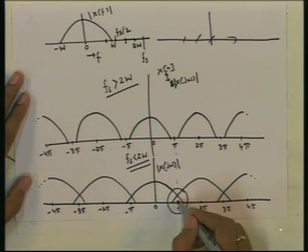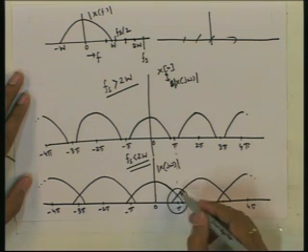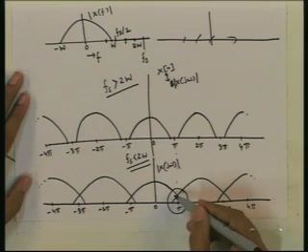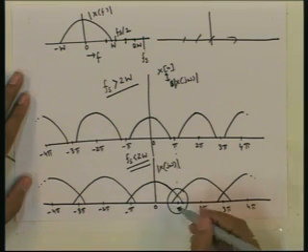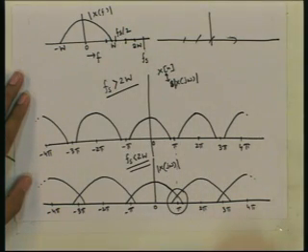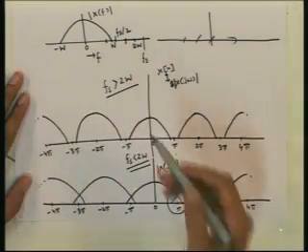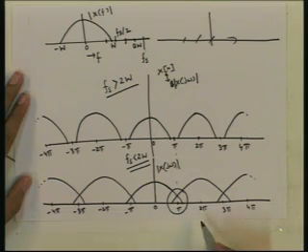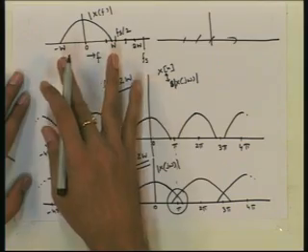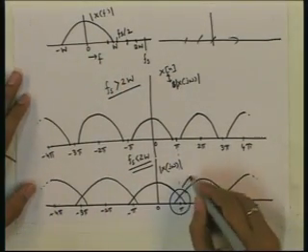Here this is just the magnitude. So when we take the sum, we have to take the complex numbers and then add. So the magnitude of that will have some shape, and it may not be possible to get these values from that sum value, and as a result we may not be able to get the original signal back, because the spectrum has some mixing of the different copies of the original spectrum, and this is called aliasing.